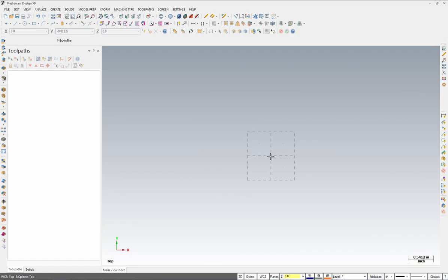Hello everyone, and welcome to Mastercam training tutorial number 3. As you just saw in the previous slide, that will be the blueprint and the CAD file that we're going to create in this tutorial. As you can see as well, I've already established my grid under configuration and grid settings, and I've changed my wireframe to a dark blue color. This can all be done in step number 1, which is setting up the graphic user interface. I'm going to proceed with step number 2.